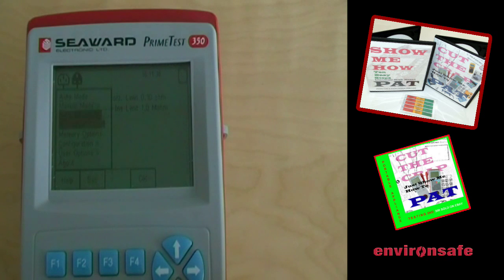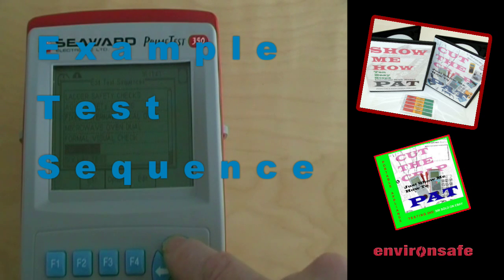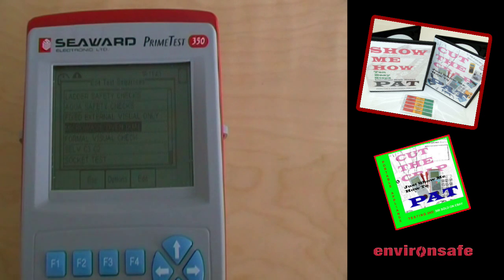F4, configuration, OK, edit test sequences, and just to show you, microwave oven dual, I've called it because of the 2 tests. F4 to edit that. We're really just looking at it, we're not going to edit it, but you can edit it in this way. Microwave oven dual as previous. Visual test, the earth continuity, the insulation and the PE conductor current.